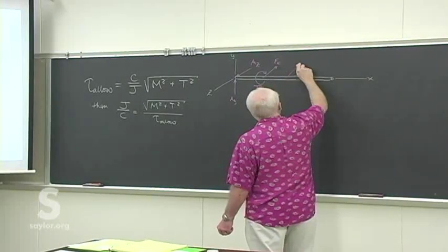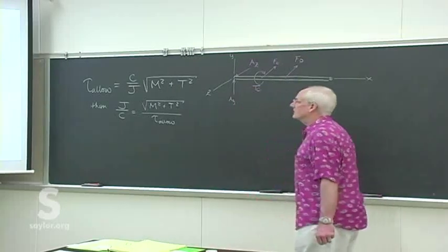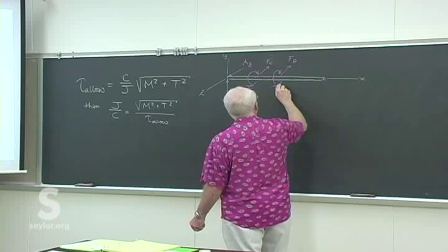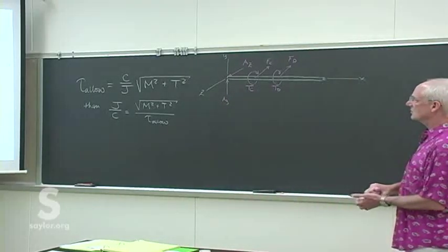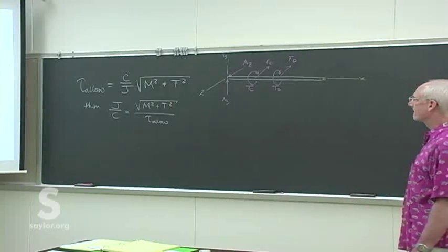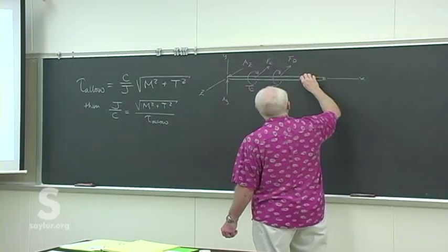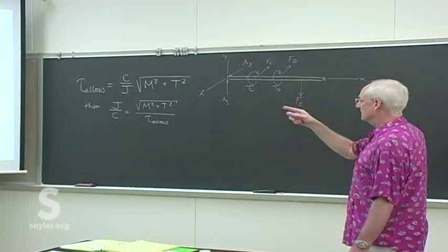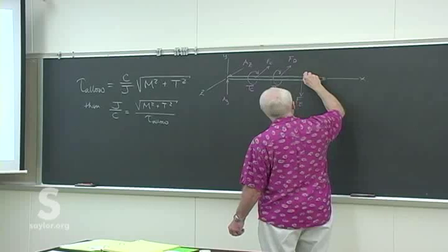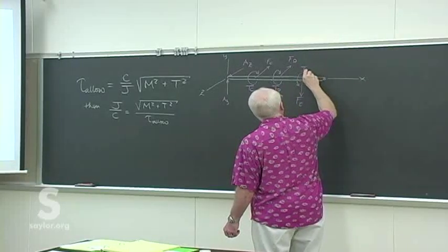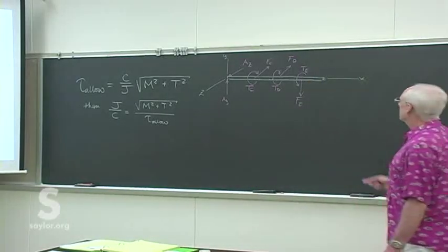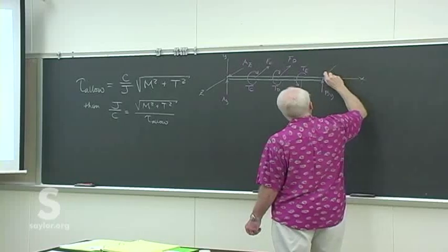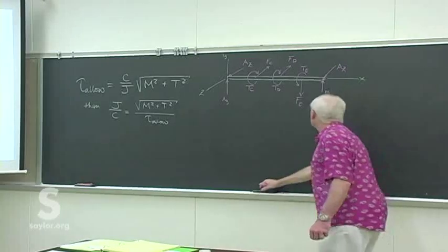Then at point D, we have another force coming off of that gear as we have power takeoff. But that's also applied at a moment arm by the gear size. So there'll be a torsion in the same direction as there was in gear C. And then gear E, due to the placement of where the motor happens to be, we'll have a force in that direction. That's F_E. I'll show you how we get that in a second with some more of the details of the problem. And then it's got an applied torsion in the other direction. And then we have the two reactions at B, again, assuming no axial load.